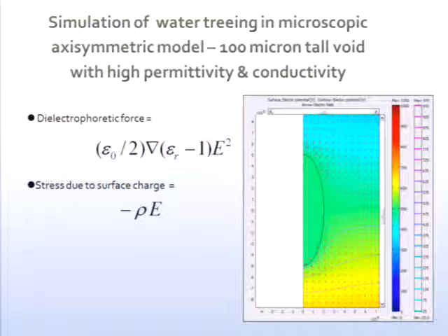So when that occurs, then what happens? It distorts the electric field. So the lines here are isopotential lines. The arrows indicate the magnitude and direction of the electric field, and you can see that in the vicinity of the poles of this ellipsoid, there's a much higher electric field than way out here. There's 1,000 volts between here and here, incidentally, in this calculation. I think it's 1,000 volts.